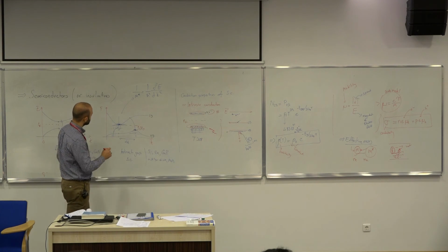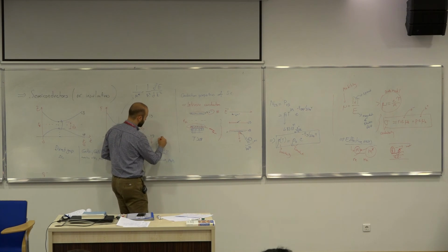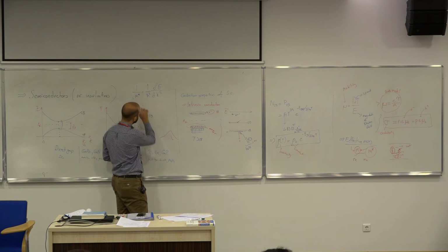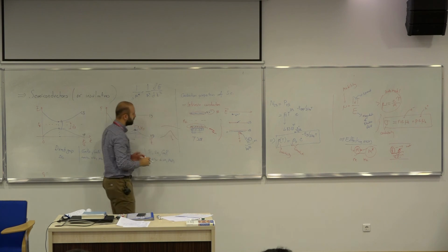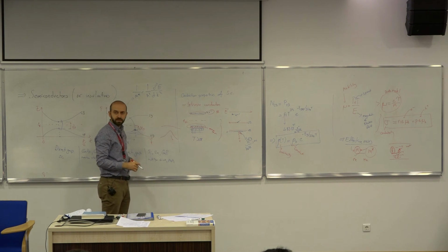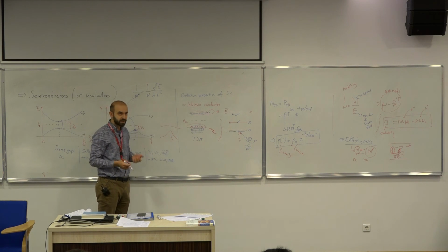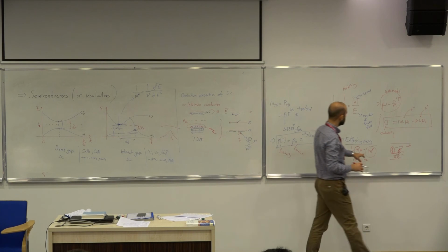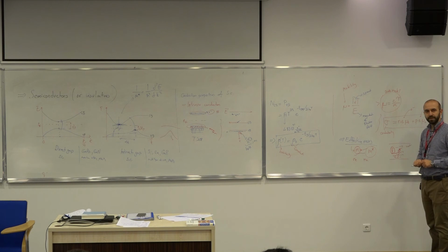If you have a very sharp edge of your energy band like this, then this means that the effective mass is going to be small. If you have a very broad edge of your band, then the effective mass of your electrons is going to be very high. So you can use these effective mass terms in the Drude model to figure out the mobilities.